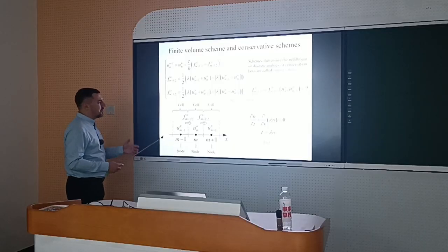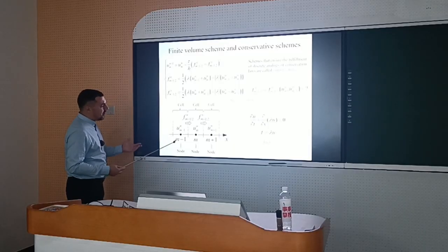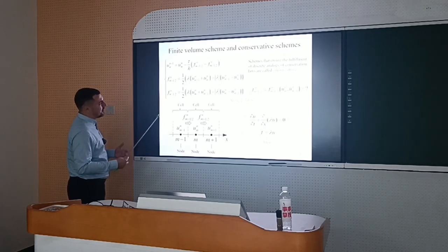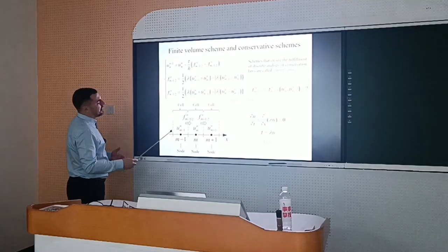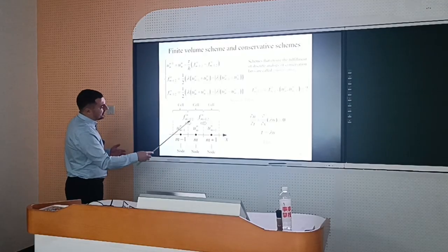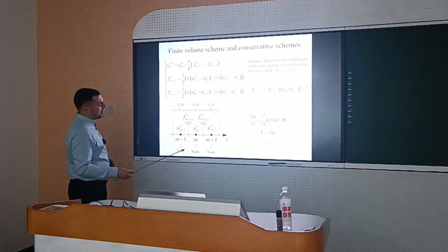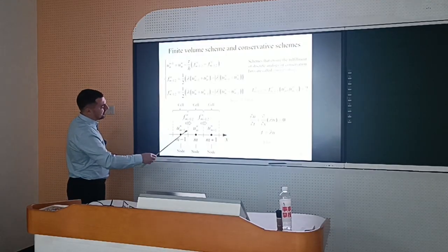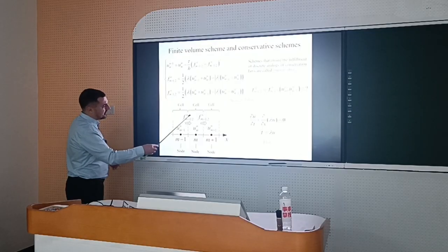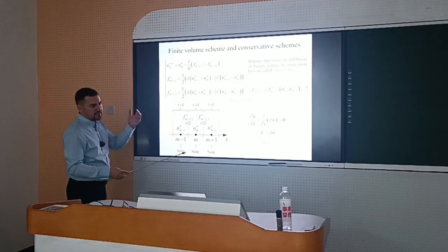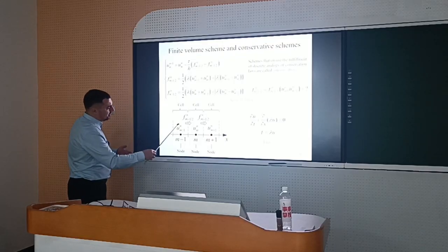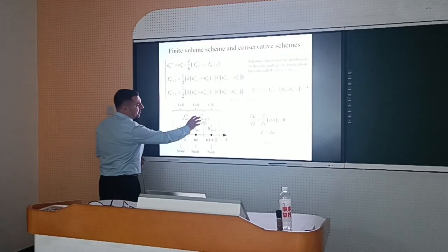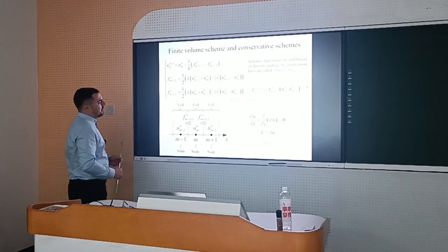Within the scope of our course, we will formulate all the numerical methods for the solution of Euler equations. So they will be the finite volume methods. In this approach, we have a computational cell, and our numerical scheme is written as a balance law for this computational cell. So the change of quantities in this cell, for gas dynamics density, momentum, and energy, is due to fluxes through the boundaries of our computational cell. And the problem is how to compute this numerical flux, right?